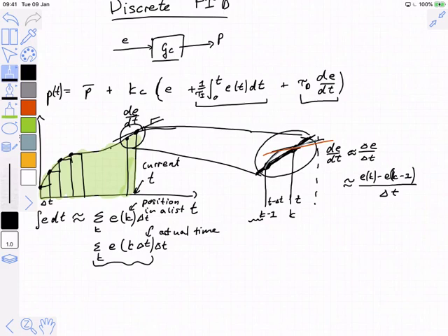This is an important distinction because I could do that if I were working offline. If I had some curve and I were just trying to approximate the derivative, it wouldn't matter whether I was going 1 time step forward or 1 time step back, or whether maybe I chose to average the values over 3 or 4 time steps in a derivative filter. Because that control unit has to calculate a new value right now and cannot wait 1 time step to gather new information, it's basically required to use the backward approximation.